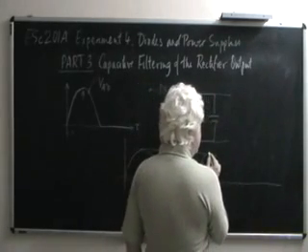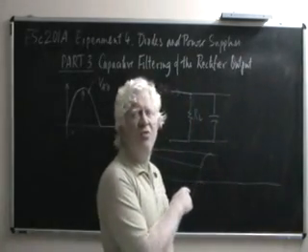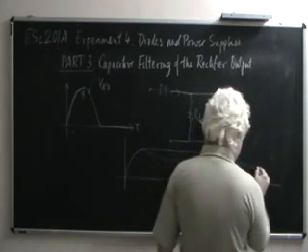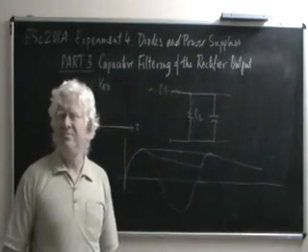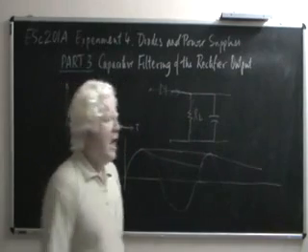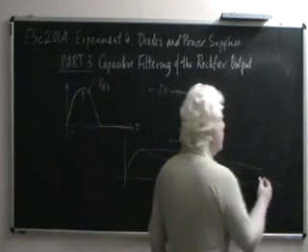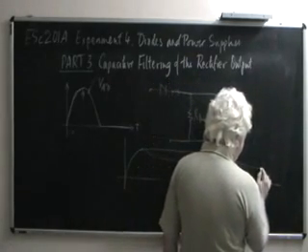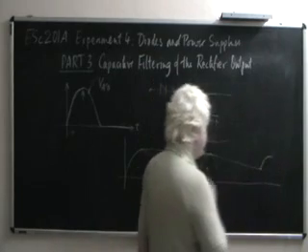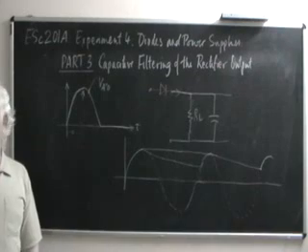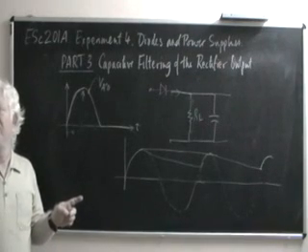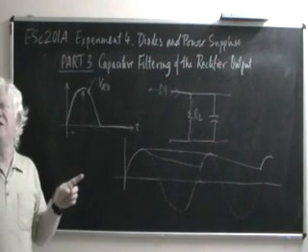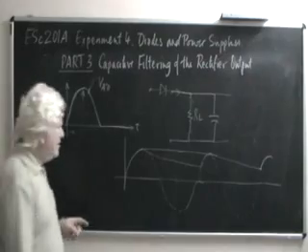In the second cycle, again the capacitor voltage droops because it discharges through the load resistance, and you get this. Again at this point, the rectifier input voltage exceeds the capacitor's voltage, and so the diode gets forward biased and it charges the capacitor. So finally, with the capacitor present, unlike the case when the capacitor wasn't present, you have a voltage which is periodic and which has this sort of a shape.